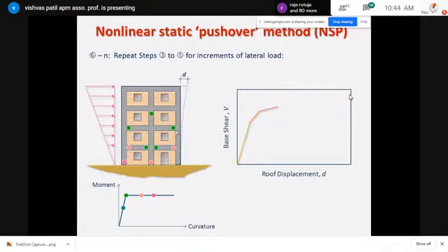Again the deformation, the roof displacement at the top, is increasing with further loading. Then with further loading, see the hinge changing color in this column. This shows a complete failure. Meanwhile, the other hinges have different colors. For example, this particular hinge is here, and this particular one is here. That means this has just yielded.